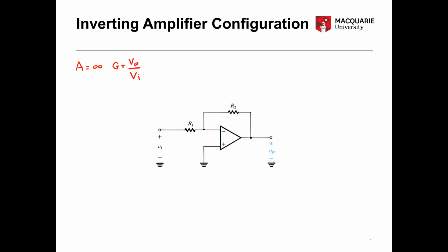So we can work this out from our circuit by simply applying some of the basic laws of electronics along with the characteristics of our ideal op-amp. And in this video we'll talk through those in a simple step-by-step basis. So step one is to very simply recognize that our non-inverting op-amp input, which we'll call V2, is equal to 0 volts. That's straightforward as it's connected directly to ground.